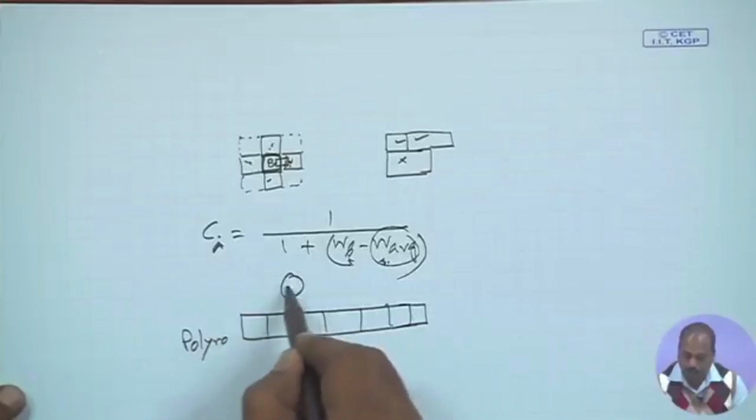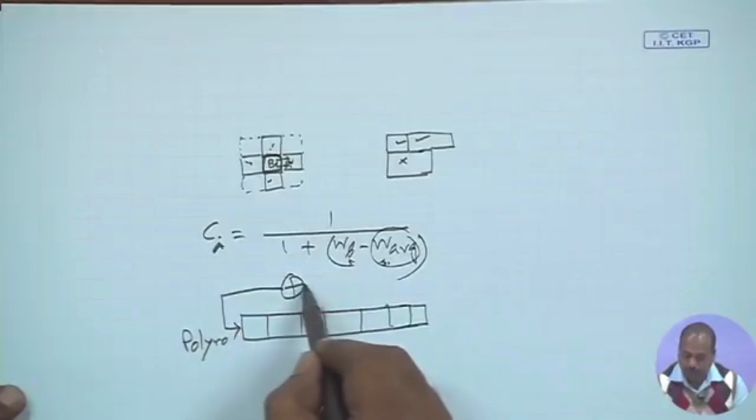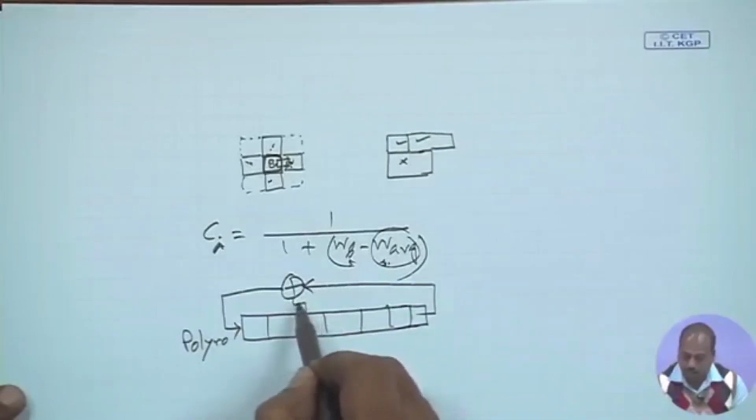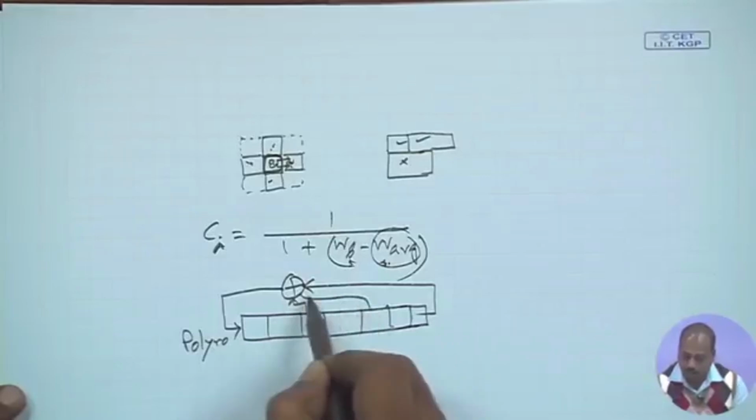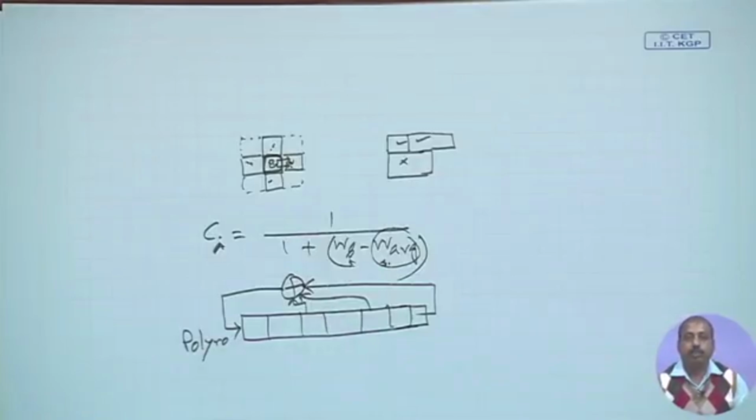There is an XOR gate, and this XOR gate feeds back to the first cell, and there are the cell positions that you are tapping. It may be that we tap these two positions and take them into this LFSR. That will tell us the characteristic polynomial. If the characteristic polynomial is changed, then it will behave differently, and it will generate a different set of patterns.